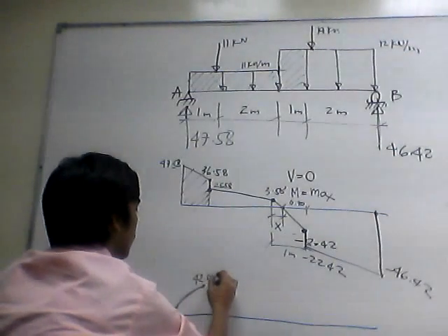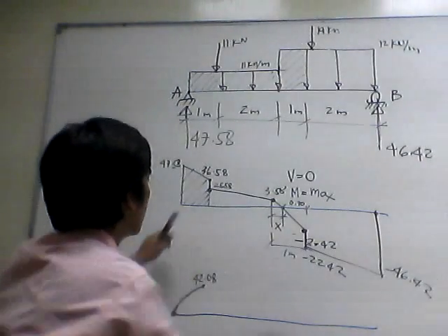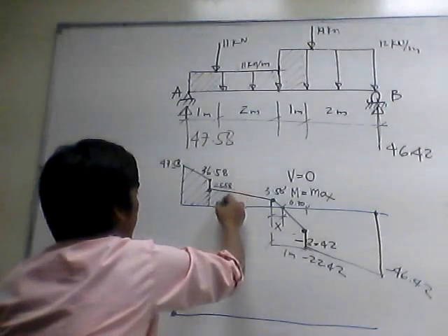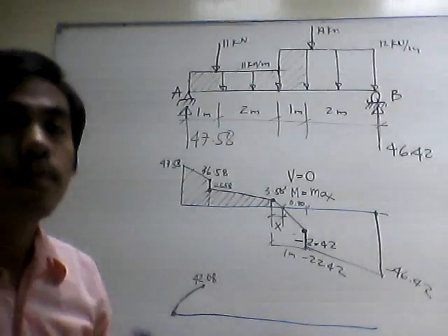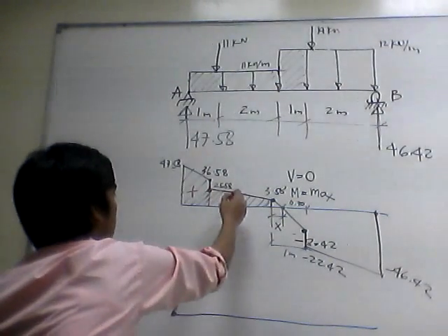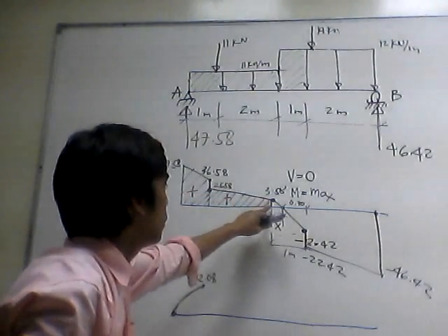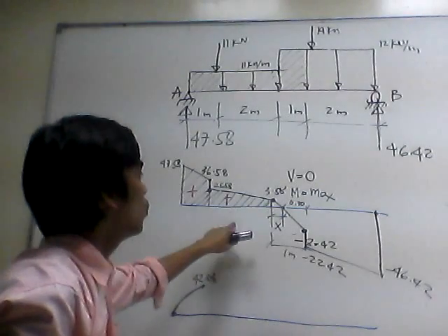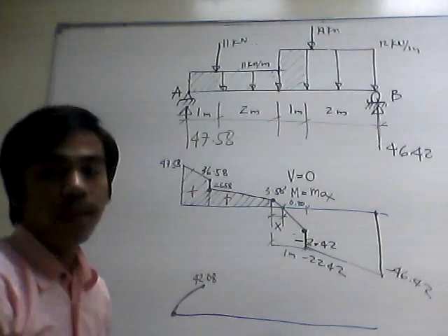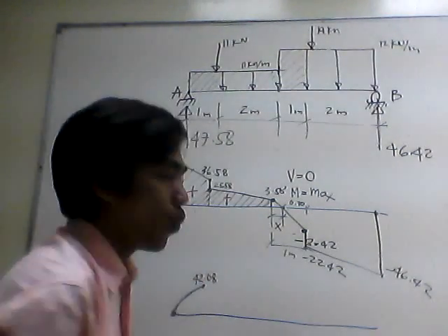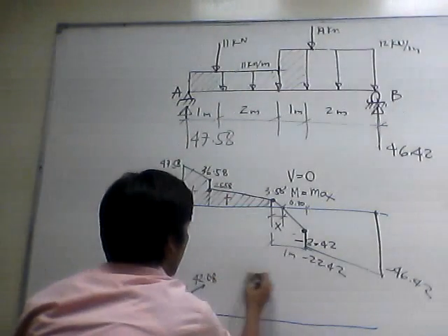Second degree curve. And next we have this area. Next area, trapezoid. So this is positive. Positive. Then we are going to add this area. 25.58 plus 3.58 times 2 over 2. That will give you, plus this 142.08, that will give you 71.24 kilonewton meter.